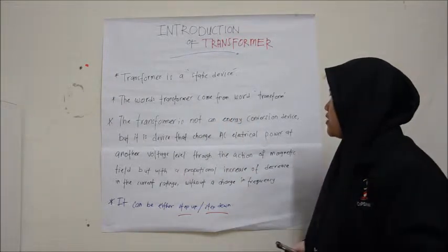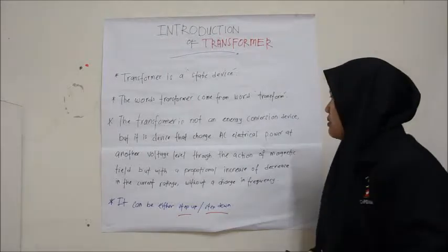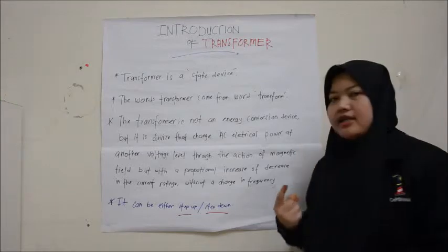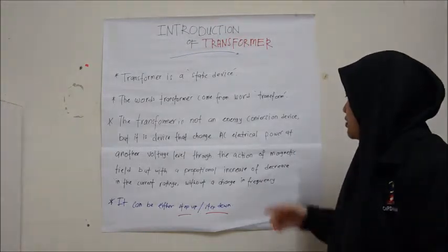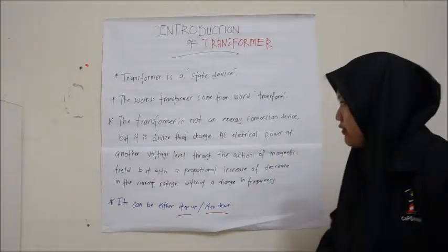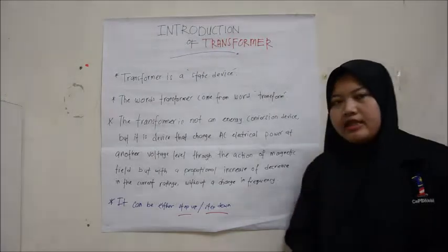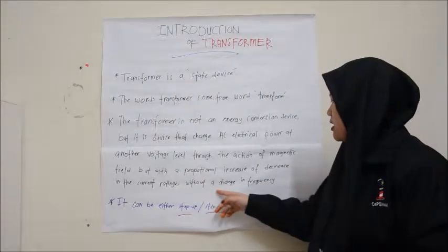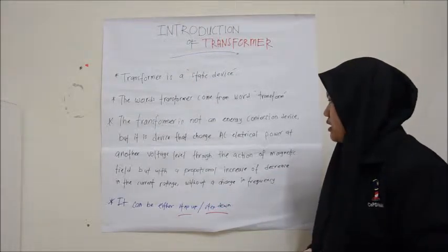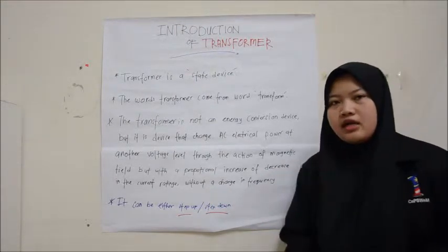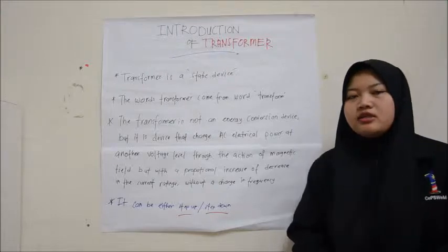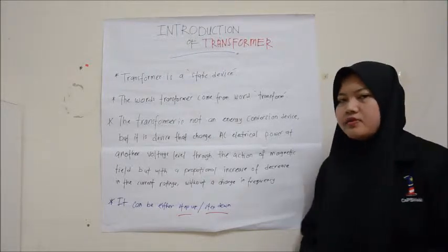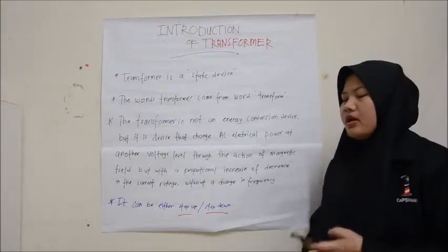The transformer is not an energy conversion device, but it is a device that can change electrical power to another voltage level through the action of the magnetic field, with a proportional increase or decrease in the circuit ratings without a change in frequency. So basically, a transformer is about changing voltage with the help of electromagnetic induction.